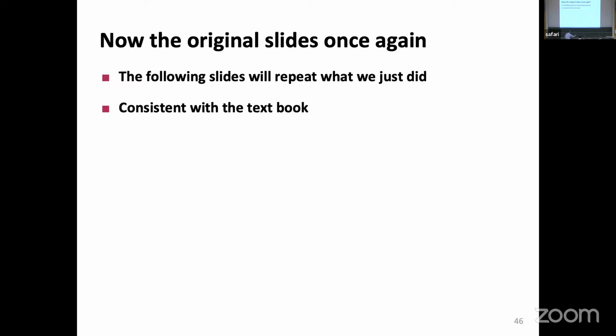So I read the register, and now I'm going back to the register. The first part is done. So this is the write update, and this guy writes this, I write it back. So this is where I write it back. I have already read, so there is no race condition whatsoever.